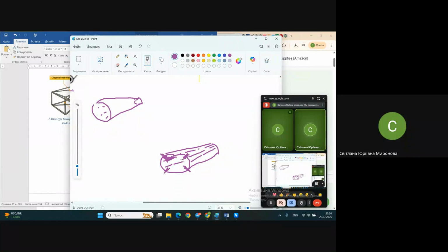They really differ significantly in appearance from the other longitudinal elements, stringers. They look like beams, in contrast to stringers. Those longerons are responsible for receiving the bending moment. Stringers are insufficient, or maybe absent at all, in this case.